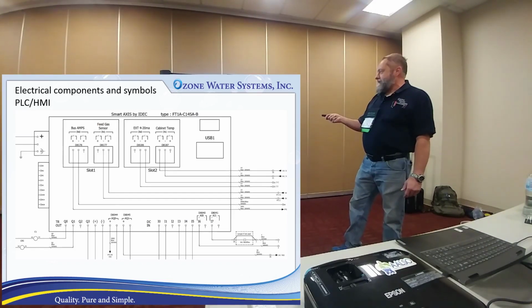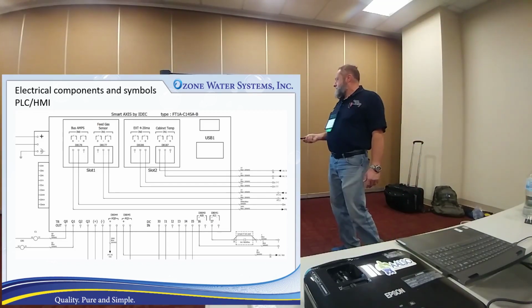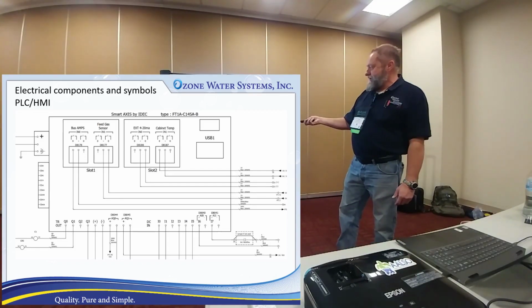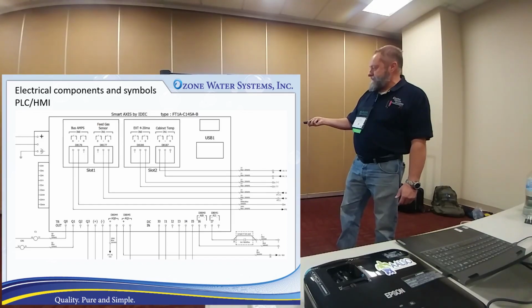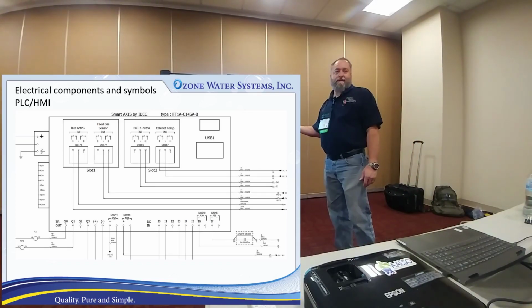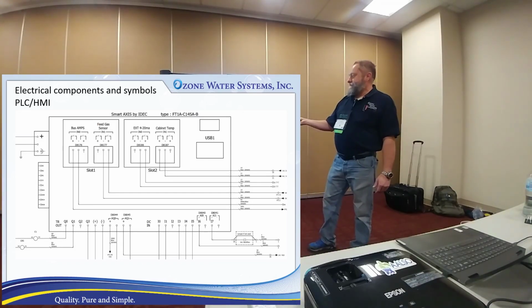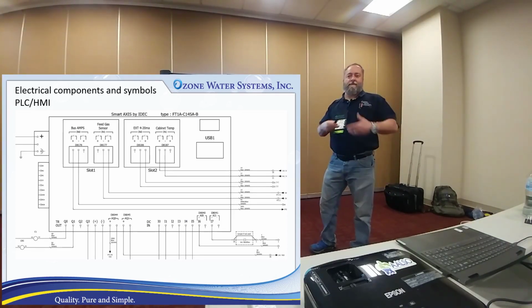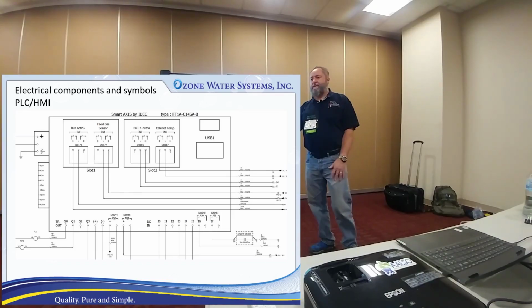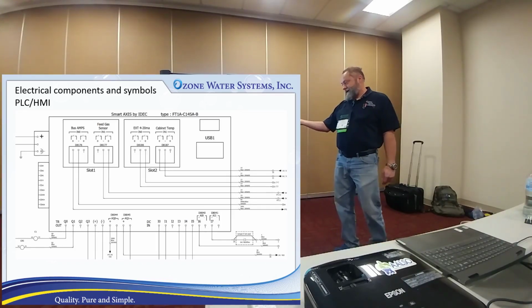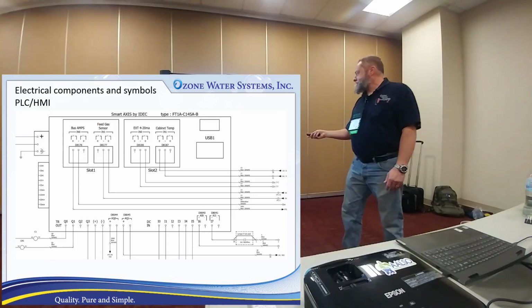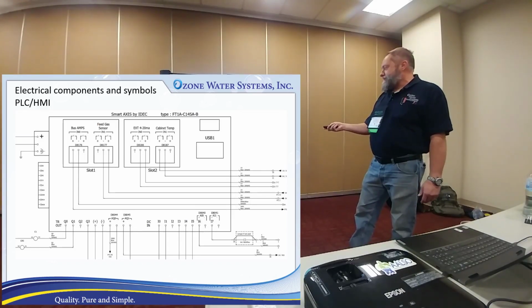It tells you what that terminal's function is. The contactors there, you can see we're turning on relays with these outputs. Now, these are relay outputs, so you really could control some of this stuff directly with the output from the PLC, but in order to avoid putting any undue load on the PLC, we'll almost always take even a relay output to another outside relay, because it's a lot easier to swap a relay than change that whole PLC if somebody fries that relay. This one does have a couple of analog outputs as well.